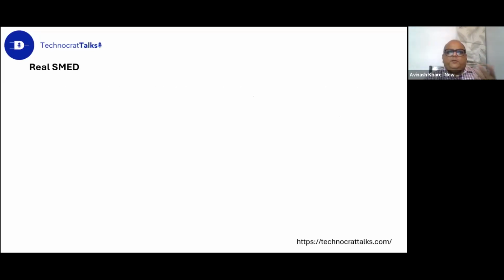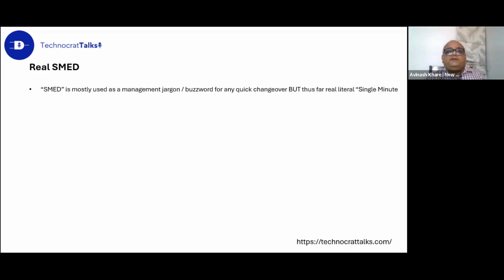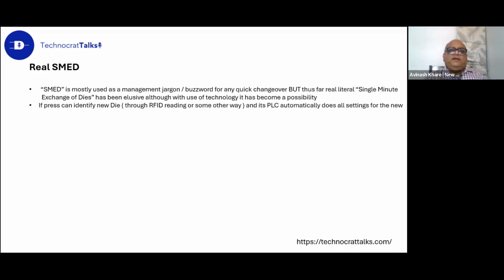Now, with industry, what has become important, in view of the high cost of a press line, is to change from part A to part B very fast. Now, real SMED, literal SMED, single minute exchange of dies. I am not talking of a management buzzword. I am talking of single minute exchange of die physically on the press.